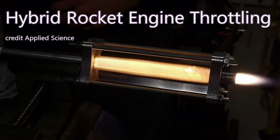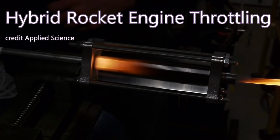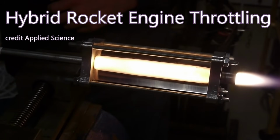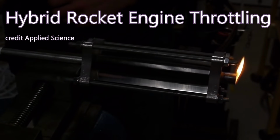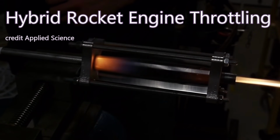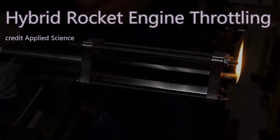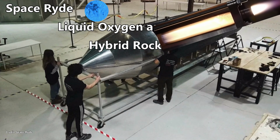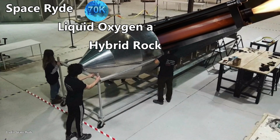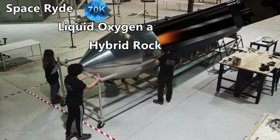A hybrid rocket does not embed the oxidizer in the fuel, like a solid rocket motor does. A hybrid rocket usually has a gaseous oxidizer. This can start with liquid oxygen, nitrous oxide, or hydrogen peroxide. These oxidizers all have different strengths and weaknesses. Nothing gives you more oxygen, however, than pure oxygen. Compressed and cooled into a liquid, it is usually at about 70 kelvins. This oxygen is sprayed down the core of the solid fuel engine.